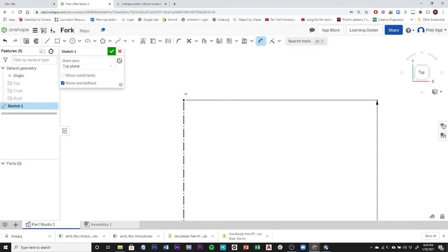So I'm going to use a number that's easy to use whole numbers with. So that would be, we're going to use 9 millimeters. So I'm going to use the construction geometry again just to create some guidelines. And I want my total length from the center, whoops, click that and then do the line tool, sorry. I want this total to be 9 millimeters, so I'm going to place it here, escape out of the line tool, and then dimension this. It's going to be 9 millimeters.